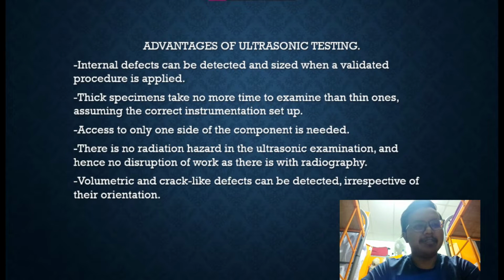The advantages of ultrasonic testing. The advantage of ultrasonic testing is that internal defects can be detected and sized when a validated procedure is applied. Next, a thick specimen takes no more time to examine than a thin one, assuming the correct instrumentation setup.